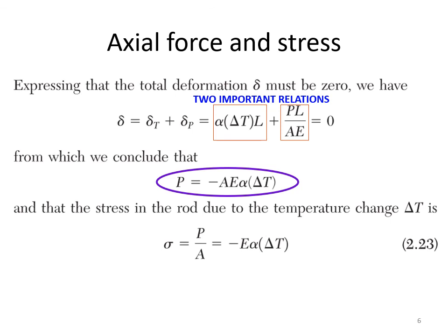The chief input parameter is the temperature change with a direct relation to axial stress. Young's modulus and thermal expansion coefficients are considered constants for a steel rod.